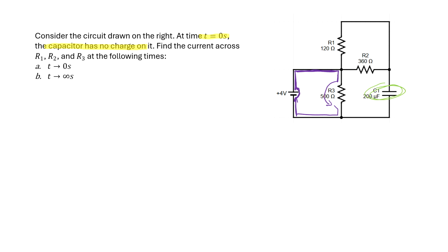If we went up 4 volts worth of elevators, in order to get back down to the ground floor, we have to go down 4 volts. And immediately, we actually already have that. There's nothing which is going to change, that we have to feel 4 volts at this third resistor. We are looking eventually to get to currents across those 3 resistor elements.